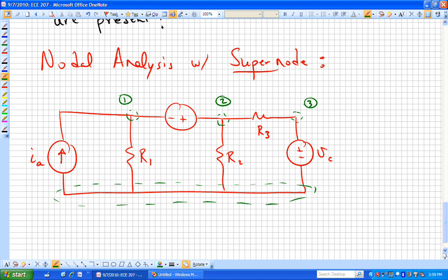If we found 3 node voltages, or define 3 node voltages, really we just need to find 2 of those that are unknown, V sub 1 and V sub 2. And we can say here's V1, and here is V sub 2. Plus to minus, plus away from the reference node, and minus on the reference node. If I'm writing KCL equations, I might be interested in that current. I might be interested in this current. I might be interested in this one. And let's say this one.